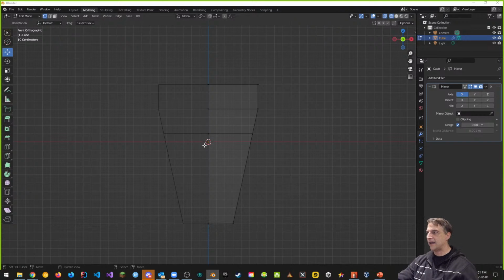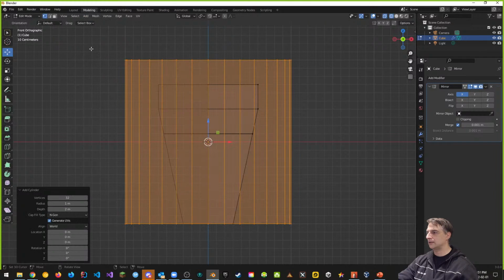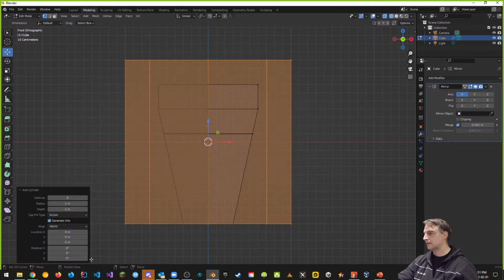I want to add a new mesh. And the way to do that is you can go to add, and you can add whatever you want. I'm going to add a cylinder, right? That's what I want to do, cylinder. Notice how big it is. It's massive. Let's also cut down the number of vertices, the complexity. Let's cut the number of vertices, or cuts, if you will, down to like 8. So 8. It's almost like an octagon, right?